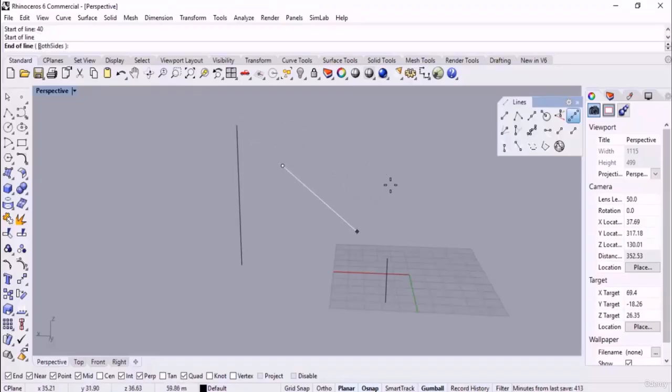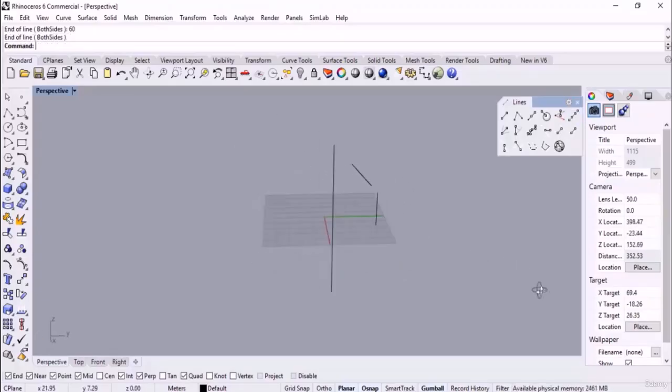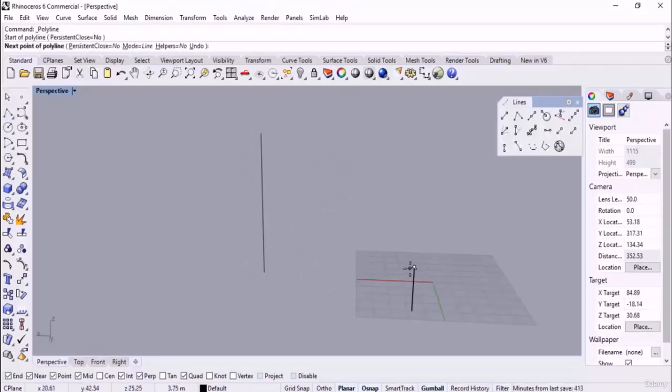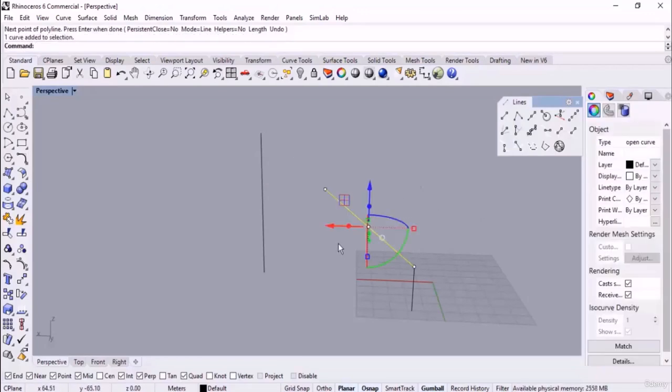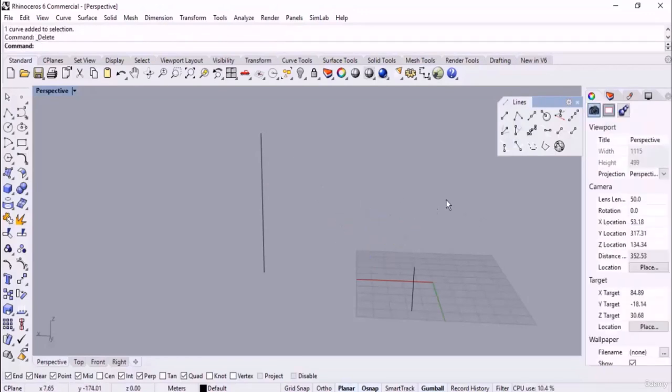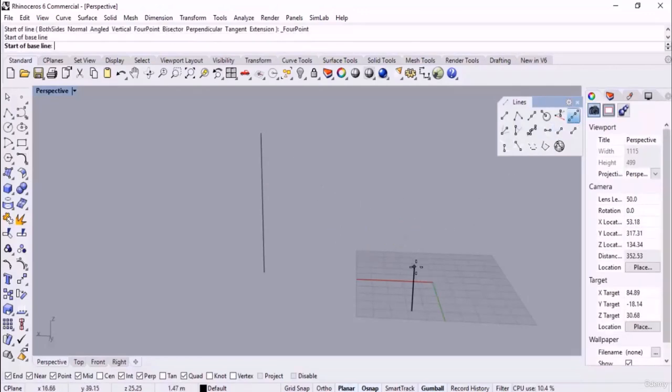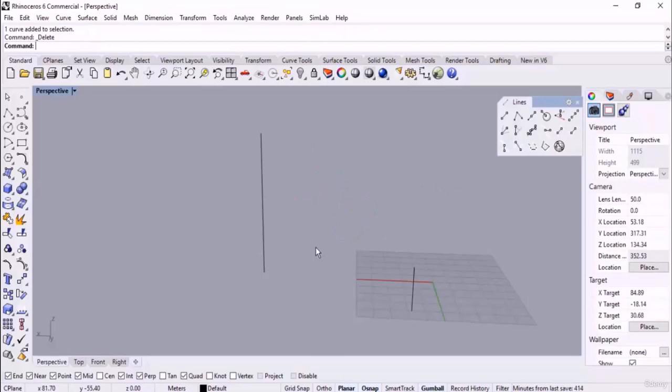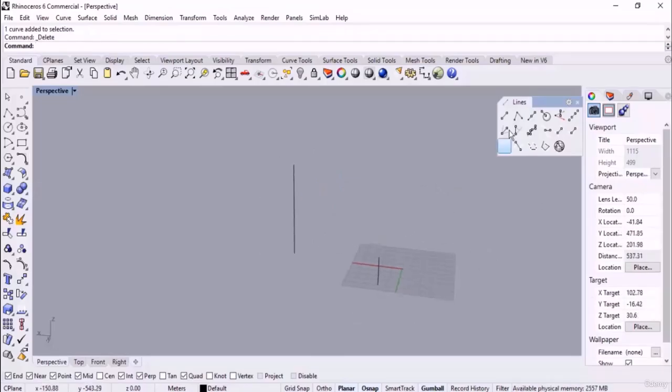As you can see, we got a 40 meters distance, and then the second length, for example 60, this way. However, we can sketch these by holding down tab, but the start point is different to the other one. The start point is connected to the previous one. But if we want to just have a single line in the scene by 4 points, the first click and then the second one in order to specify the distances and then the length this way.